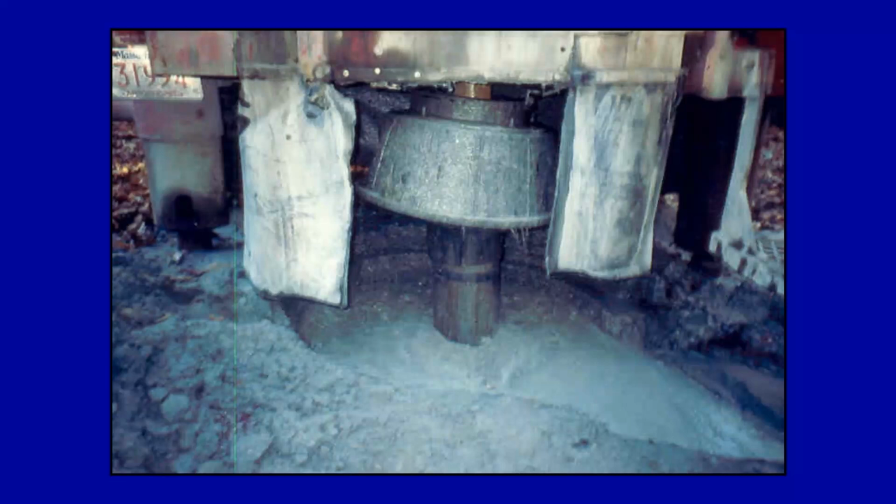Here's a typical rock well. In New England, we have to have a seal of neat cement usually, so a driller will start off oversizing a hole and then will put casing at least 15 feet into competent bedrock. When the casing is sealed in place, then a smaller diameter bit is usually drilled down to see if fractures are encountered and what the preliminary water chemistry may be.